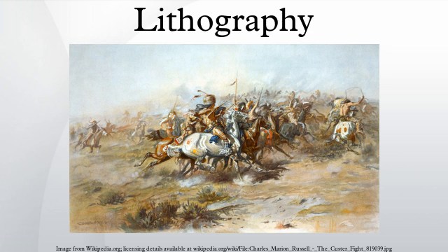Photolithography generally uses a prefabricated photomask or reticle as a master from which the final pattern is derived. Although photolithographic technology is the most commercially advanced form of nanolithography, other techniques are also used. Some, for example electron beam lithography, are capable of much greater patterning resolution. Electron beam lithography is also important commercially, primarily for its use in the manufacture of photomasks. Electron beam lithography as it is usually practiced is a form of maskless lithography, in that a mask is not required to generate the final pattern.